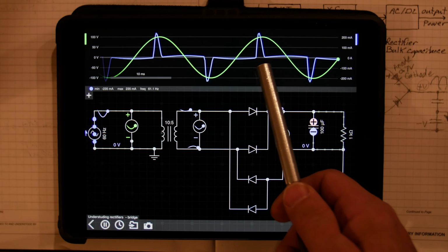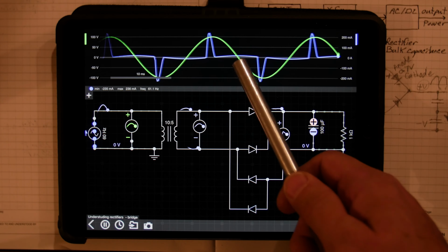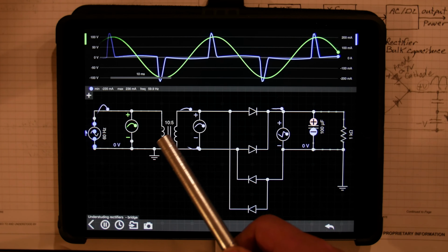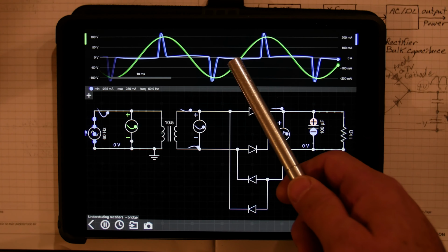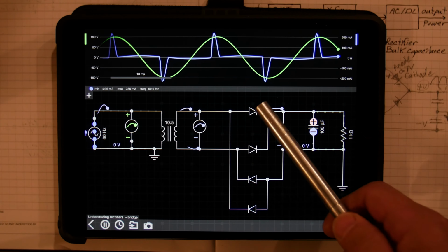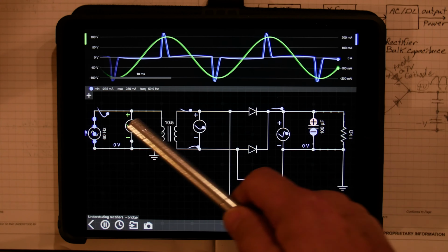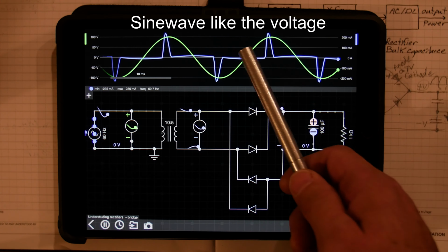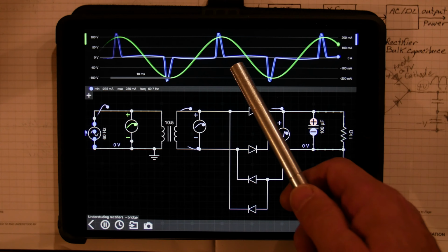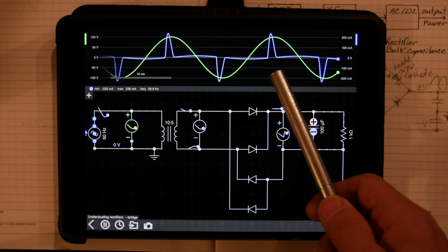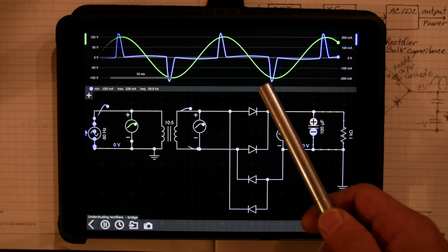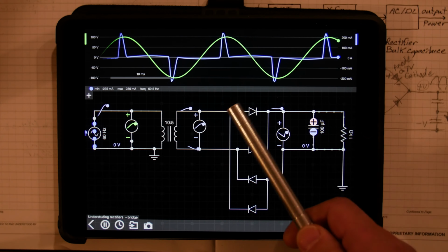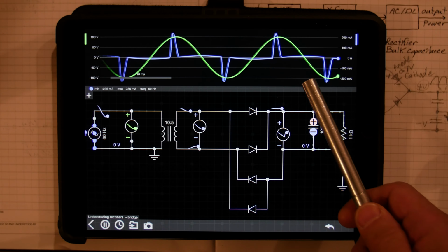And if you ever studied power factor in school, you would know that without the rectifier diodes, you'll see the current is an AC waveform just like the voltage. And depending on if they're in phase, happening at the same time, or if they're offset, you get a power factor, a phase angle. When you add rectifiers, you get these pulses. It completely changes the power factor analysis.